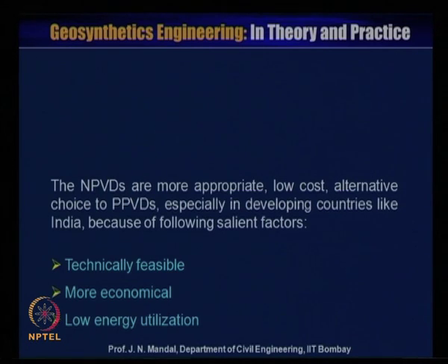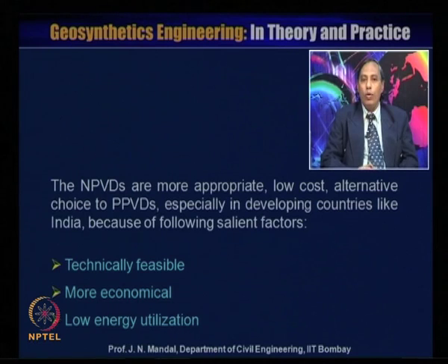Apart from this, the natural prefabricated drains are a more appropriate, low cost, alternative choice to polyester prefabricated drains, especially in developing countries like India, because of the following salient factors: the natural prefabricated vertical drain is technically feasible, it is more economical, has low energy utilization, and it is a sustainable, eco-friendly and environmentally friendly material.